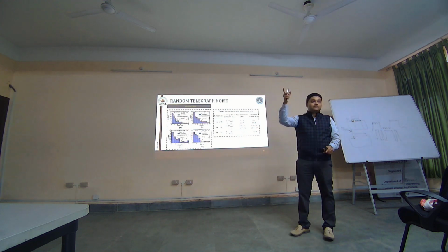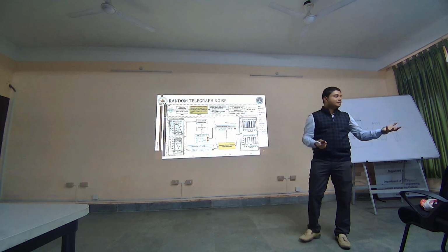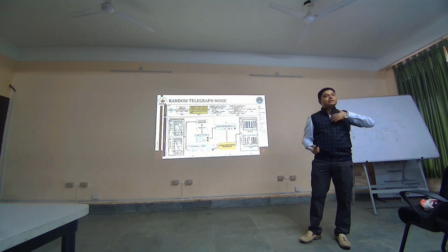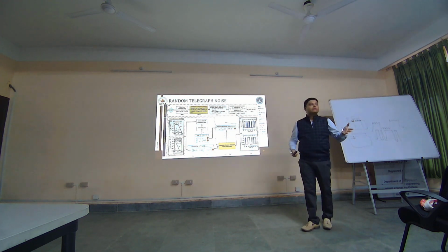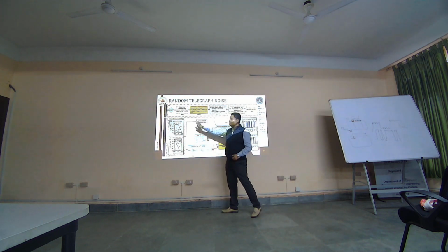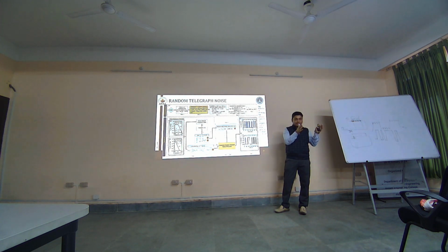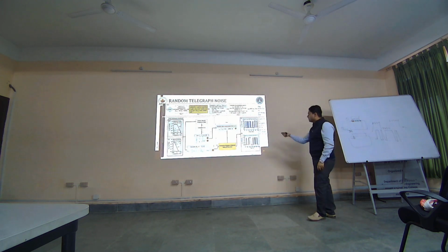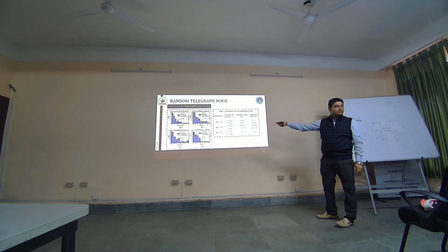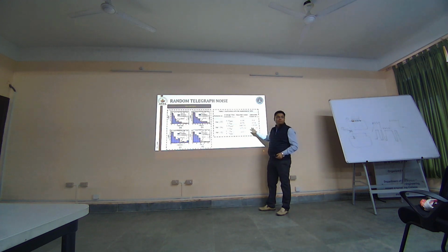After that, if you observe this method that we developed, we started with TFETs, but we realized that this can be applied to any kind of device, because here you do not have any one parameter which is only unique to TFETs. You are just simply extracting the noise spectral density, and after that you are extracting the parameters and getting this. So we tried looking at different devices which were not TFETs, and there also we found reasonably acceptable matches between our results and the results which they have.